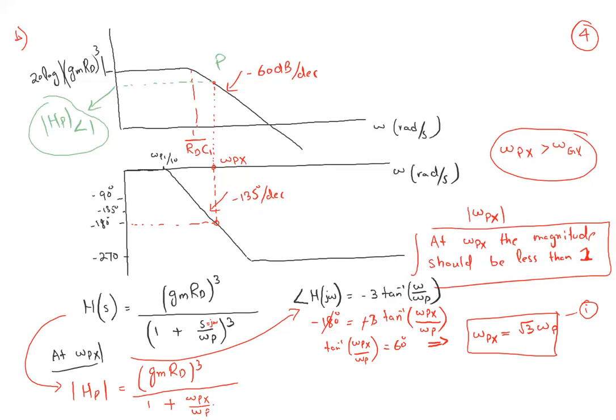Okay, now you might be seeing something, and what I need to write is the magnitude, so square root, and then we have to have a cube. So make sure this thing is clear again. Okay, so I will go on the next page and write both of these again, and then start from the same point. So we concluded that one expression was the omega px phase crossover frequency equal to √3 omega p.